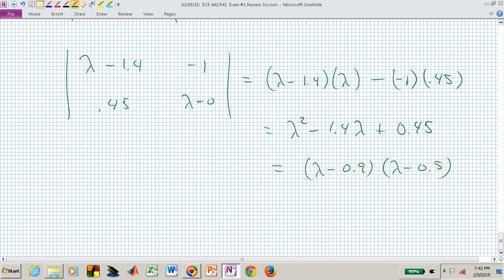You now have a pole at 0.9 and a pole at 1/2. Which one dominates? And when I say which one dominates, I'm really meaning which one tends to linger the longest in a transient response. Which one is the slowest acting?